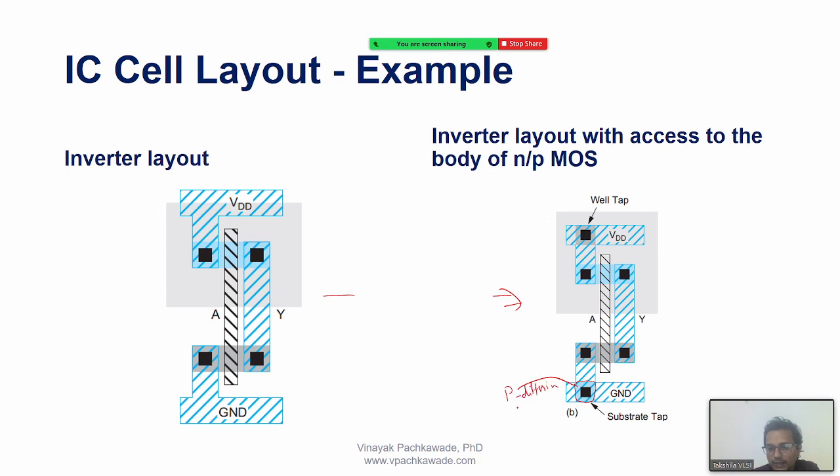I did the fabrication procedure just like in the previous session. I performed those steps and I got this dopant here, and then when I put this metal here, through these contacts 1 and 2, I got this contact etching, so metal got connected to this p diffusion area. So I would say that I got connected to the p substrate. Here is my p substrate also. This is n plus, this is n plus, and this is p plus, if you remember. So I got metal now connected to the p substrate.